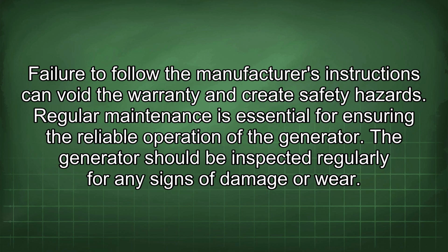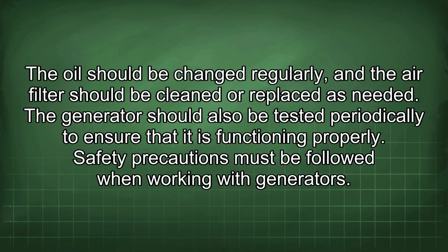Regular maintenance is essential for ensuring the reliable operation of the generator. The generator should be inspected regularly for any signs of damage or wear. The oil should be changed regularly, and the air filter should be cleaned or replaced as needed. The generator should also be tested periodically to ensure that it is functioning properly.